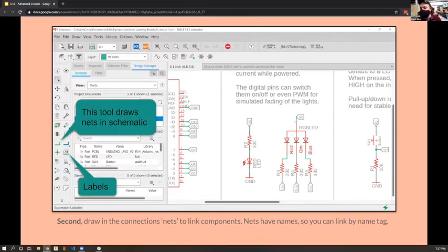So one of the things that works in both is that you can put in labels instead of having wires that go everywhere all over things in a complicated mess. Every wire has a name in Eagle and KiCad. So you can put a label like 5 volts on a wire, and then it would be connected to all the other wires with the name 5 volts. Putting a label on them is pretty much essential at that point so that you can keep that all connected. And then you can see down across the bottom, I've got D9, D10, and D11, trying to keep track of what Arduino pin these are going to connect to. So you can absolutely use labels to your advantage in schematics and all of these things if you're trying to draw out your circuits.